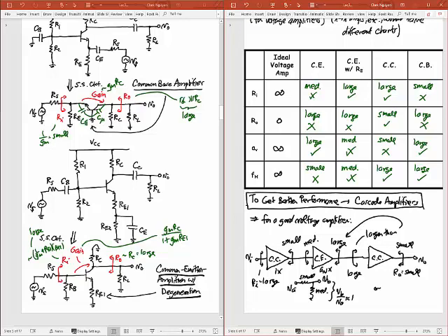Right? So here we're looking at this. R naught equals 0, or something very small there. And you have some Ri. In this case, the gain is about equal to 1. Okay? So that's how we cascade these stages in order to get whatever gain and frequency response we want. We're doing that because we know about the common base, common collector, common emitter with degeneration stages, and we're just going to use different combinations of those stages to get what we want out of our circuit there.